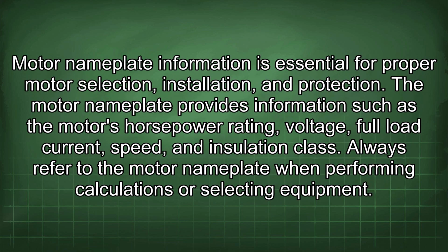Motor nameplate information is essential for proper motor selection, installation, and protection. The motor nameplate provides information such as the motor's horsepower rating, voltage, full load current, speed, and insulation class. Always refer to the motor nameplates when performing calculations or selecting equipment.